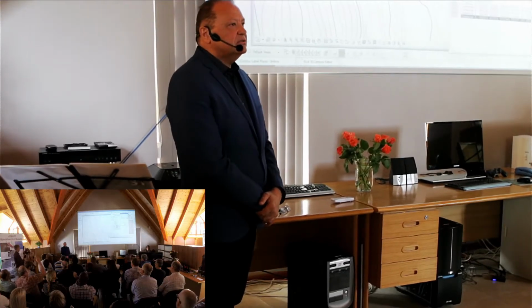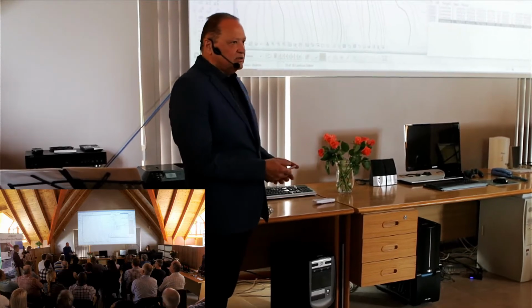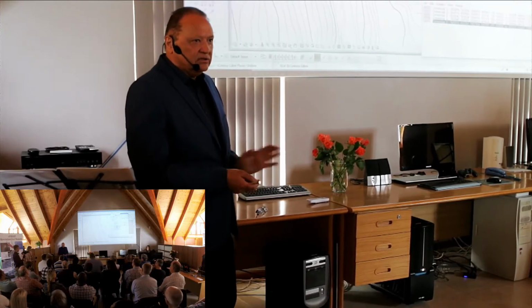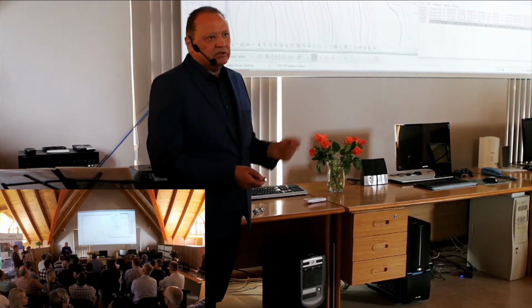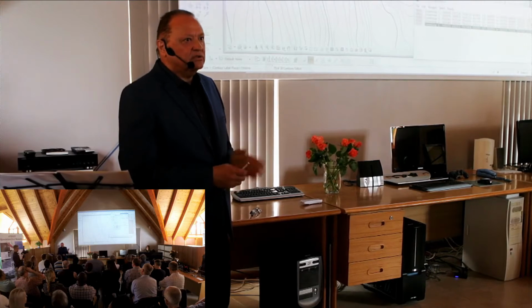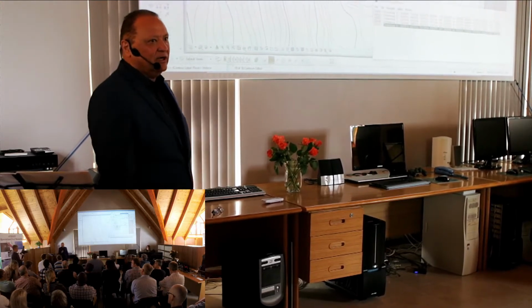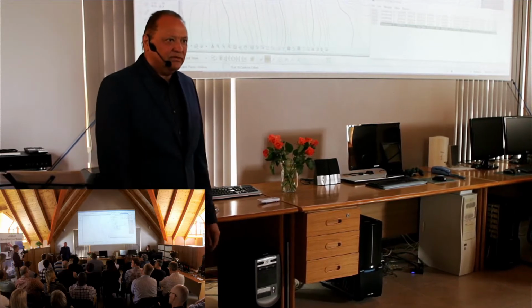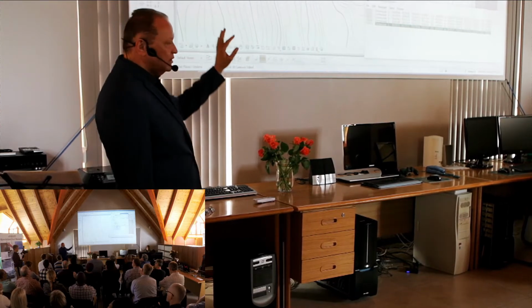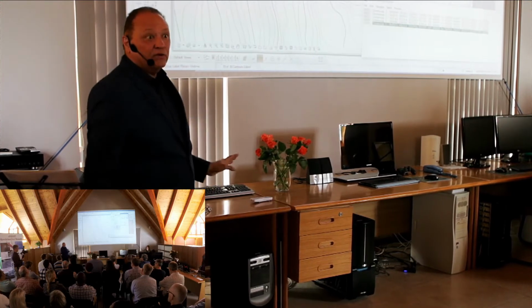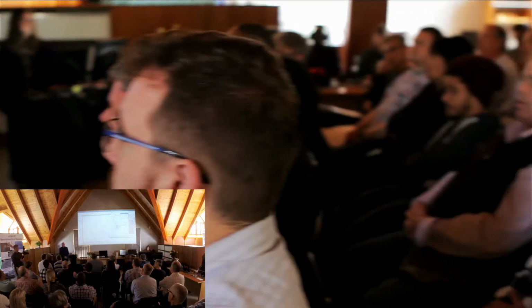I know it's quite a hassle because you would either have to have switched on AccuSnap or set your active Z or whatever. Now you don't worry about it at all. You just pick the contour and it's got the height of the contour and it's moving X or Y. There's a move option where you specifically say move X, Y, and Z, but the default is not to move the Z. Okay, so you're only moving the X and Y. So if you looked at that three-dimensionally, it doesn't matter what angle and what view. You could do it in isometric, it wouldn't matter. It would move it in the X and Y, yeah.